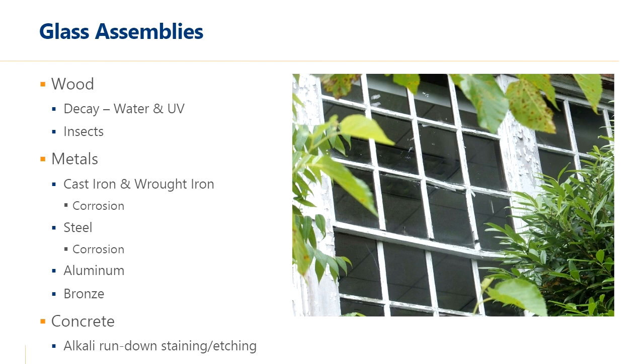Historically, the glass was captured into wood frames. Typical deterioration to be considered are wood decay from water exposure, wood degradation from UV exposure, and potentially insects. This can lead to loss of materials and, if at support members, loss of glass. The photo I have here shows a horizontal muntin and meeting rail sagging, which is also separated from the vertical muntin.